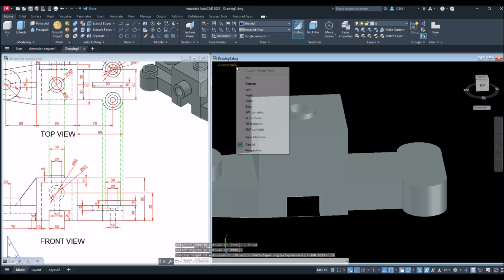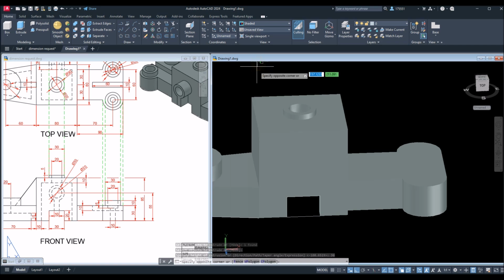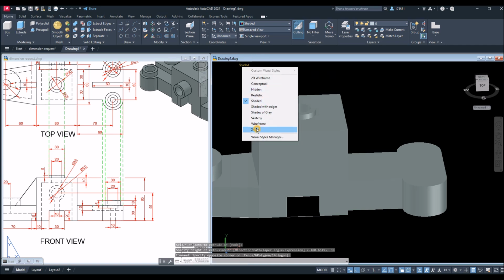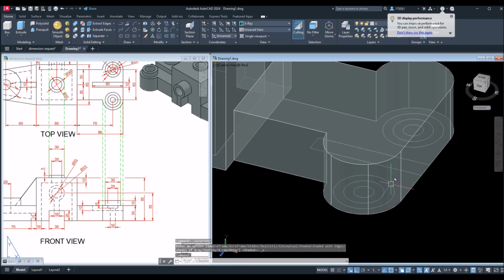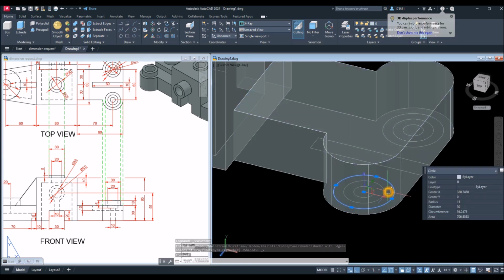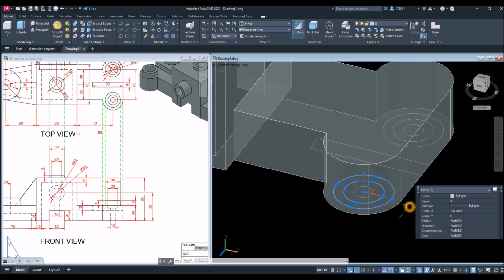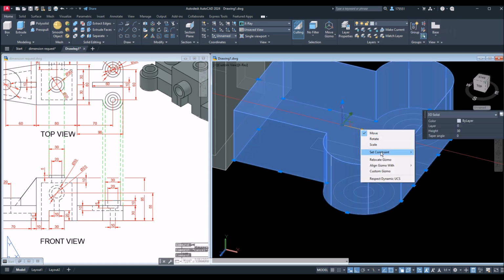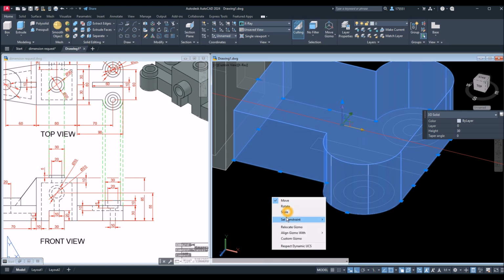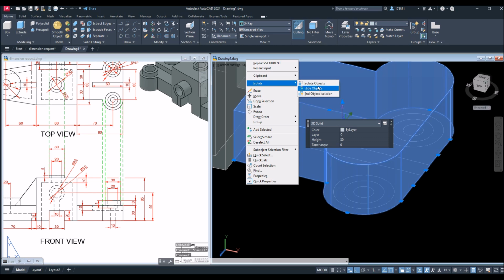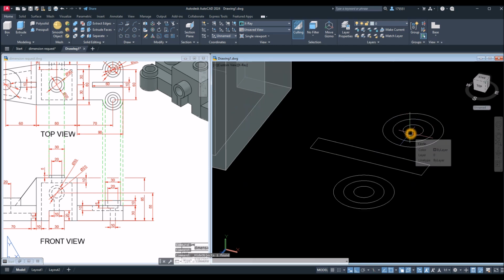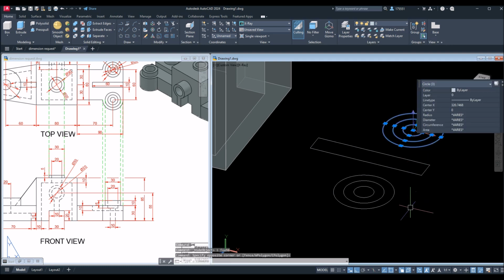Just gonna change this to X-ray. I need these guides, so the circles, I'm gonna hide this one first. Hide, it's easier. Select the object to hide, right click, hover over isolate and select hide objects. Oops. The height is 30, so I could just move these ones.